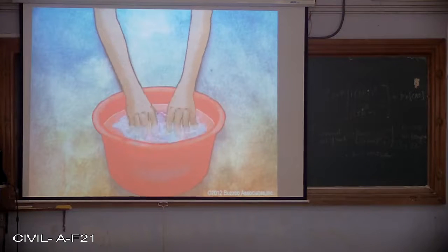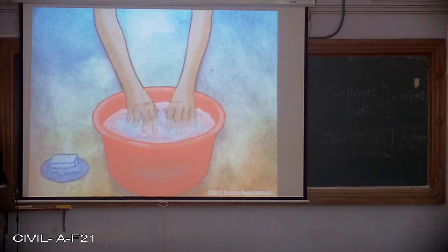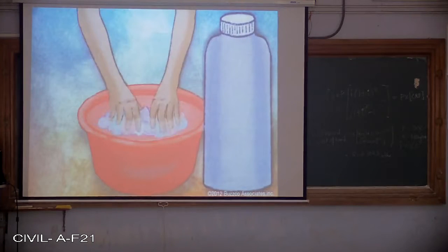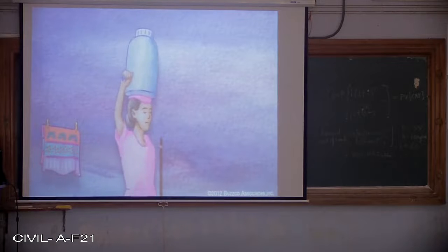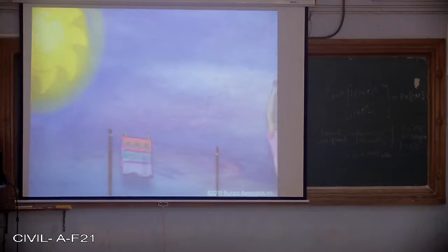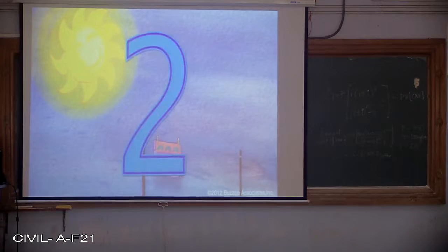Rinse the filter cloth after each use and wash with soap if available. Make sure your final rinse uses cloth filtered water. This cloth method can be used on its own, but it's better if it's used in combination with the power of the sun. Step 2.